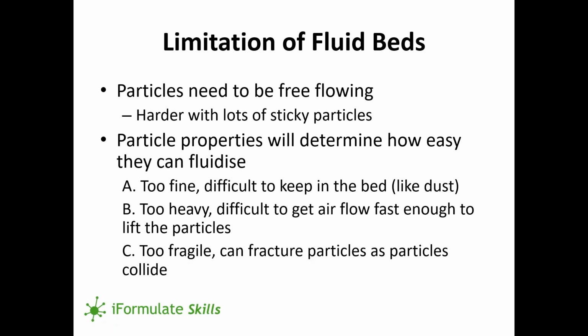The particle properties are very important in a fluidized bed, and that can determine how easily they can fluidize and be processed. If they're too fine, then it's difficult to keep them in the bed, and it's difficult to get that control on the porosity of the bed, so they behave a bit like dust. There are ways around it, just like with anything, but you are getting to the limits of fluidized beds. If the particles are too heavy, which is particularly so as they grow and become very big in size, it's difficult to get the air to flow fast enough to lift the particles. And so you often get very high flow rates with heavy particles, and it makes things harder but not impossible.